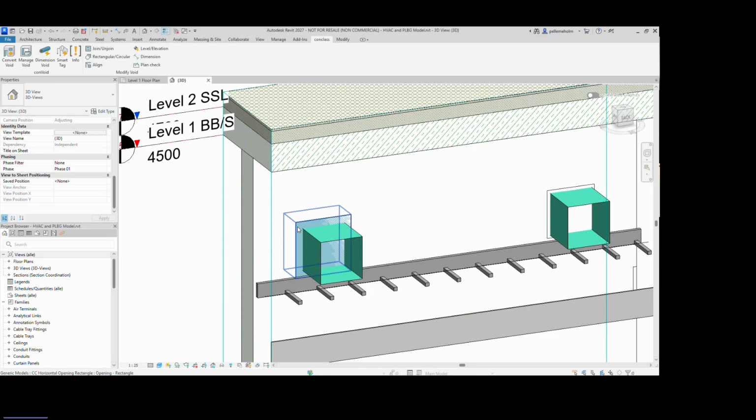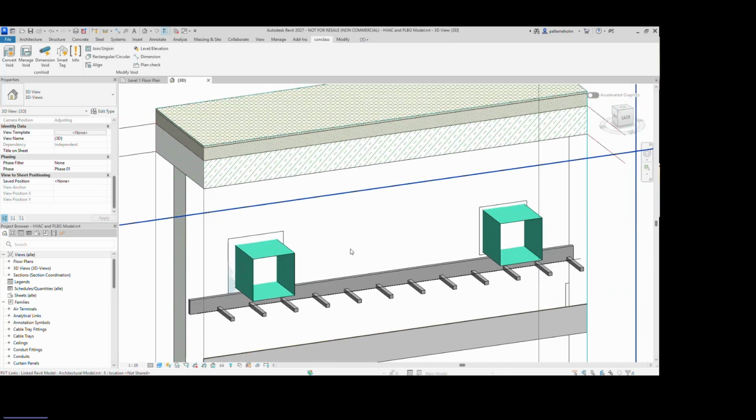This is a weakness spot regarding fire safety. So it also has to be ensured that this clearance is considered. And my recommendation is always to say 50 millimeters. That's enough clearance to ensure you can seal the entire opening, and all the sealing mass will seal the opening.